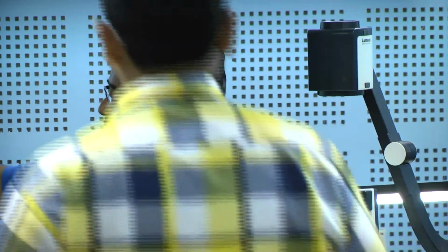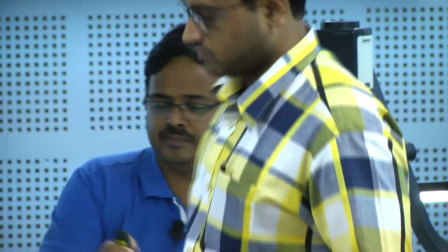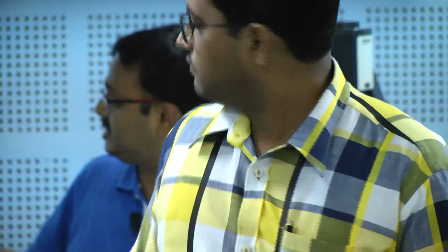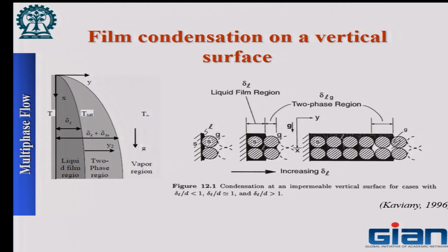And again, keep in mind, entirely we are talking about porous media. All these layers are inside the porous medium. So, as I move away from the wall, I will first see a layer which is only liquid, followed by a layer which is liquid plus vapor, and then only vapor. So, that is how it is. And therefore, now things become a little more complicated, because I have to analyze the continuity, momentum and energy equations for both of these layers.